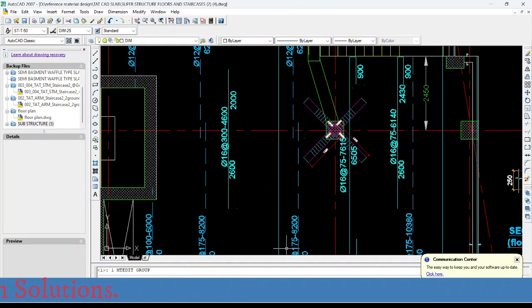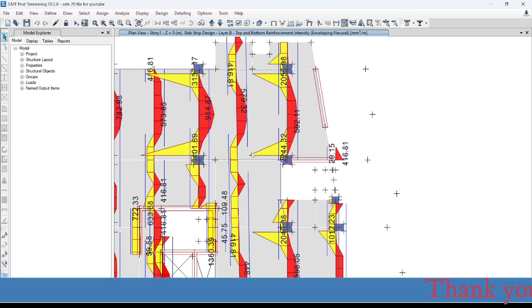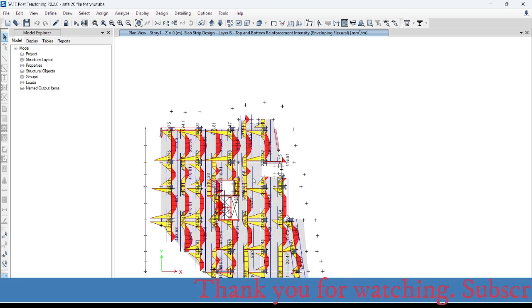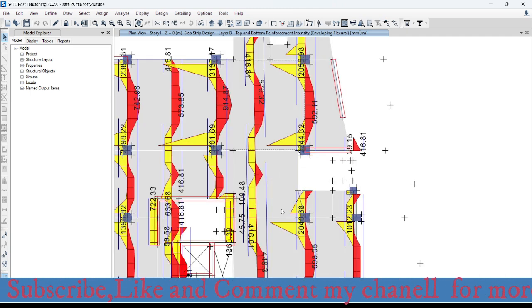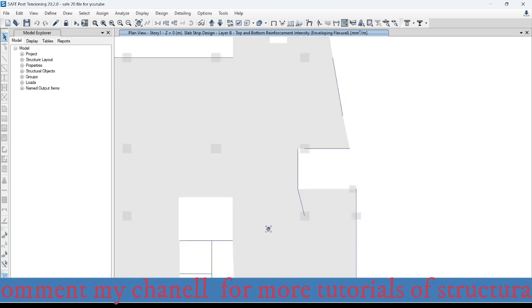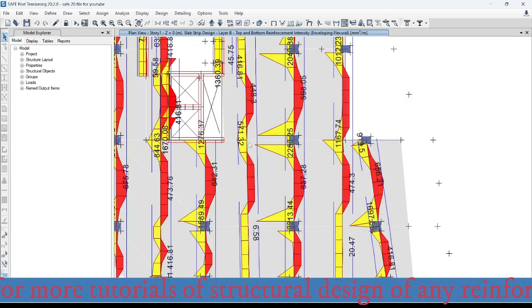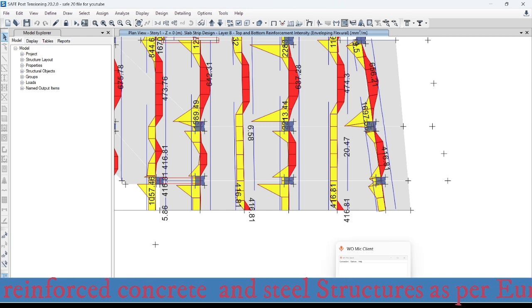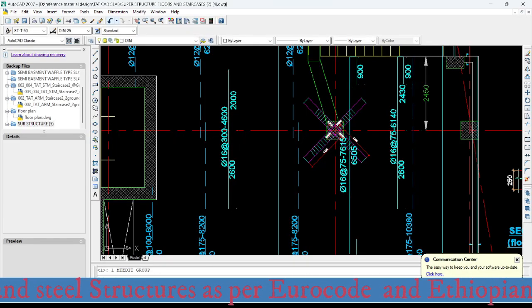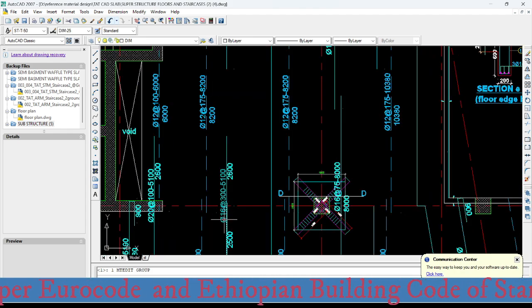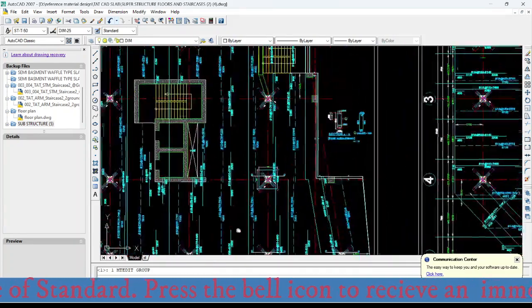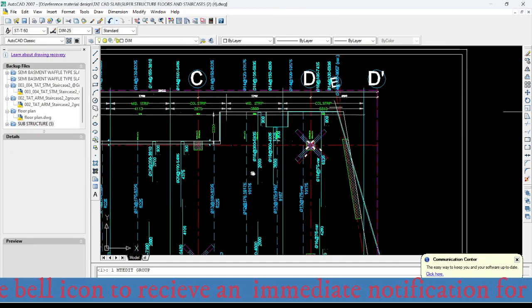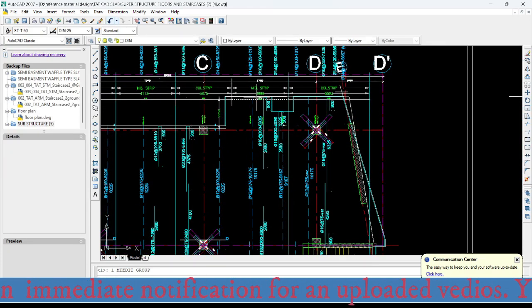Now the third support, which is also the same. The third support is around here. It is also the same. So I can use the same reinforcement area, and this one is also the same reinforcement area. So throughout I can use the same negative reinforcement area. That is diameter 16 with center to center 300, throughout. So now let me come back to the positive reinforcements, or the bottom reinforcement detailing works of the